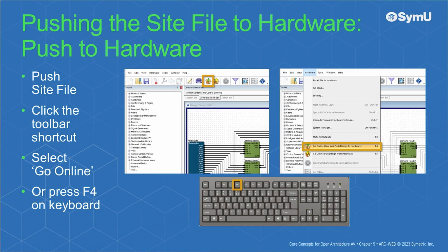The next step is to push the site file. To push the site file, either click the toolbar shortcut, select Go Online, Push Design to Hardware from the Hardware menu, or press F4 on the keyboard.